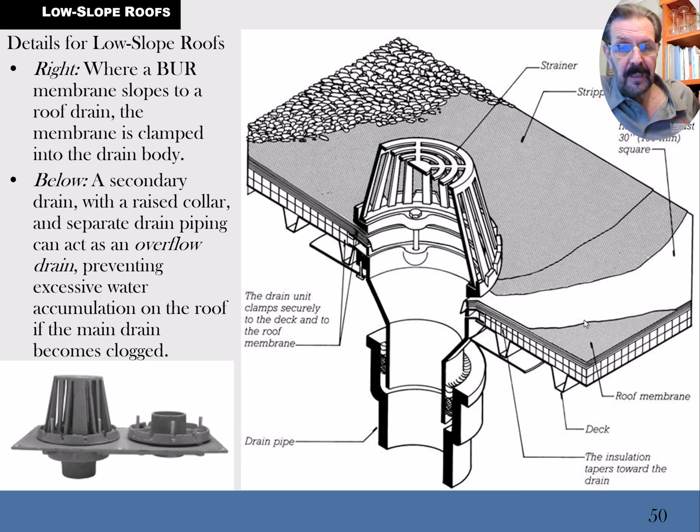Because when you have a pool of water, a lot of these roofs aren't going to be good enough to keep it back like a pool liner would, to keep the water from finding its way through some flaws somewhere along the way in the roofing material. So it's important to keep these strainers clear, but also make sure you really have strainers up there and not anything missing over time. This roof building was ancient, so who knows what reason they were missing the strainer.